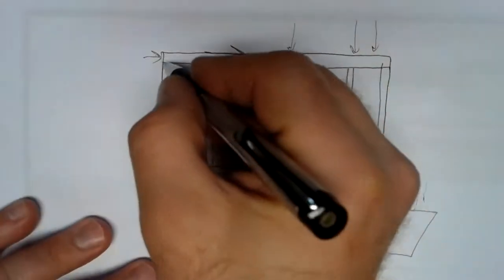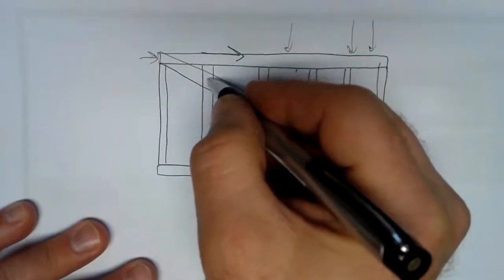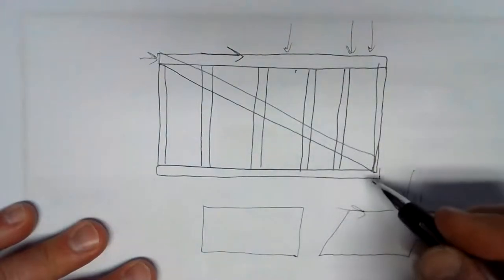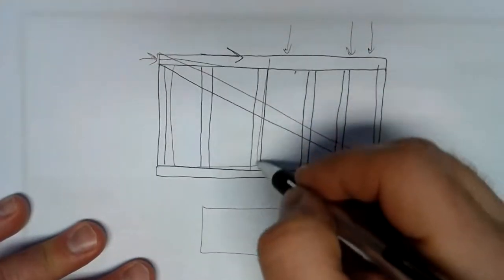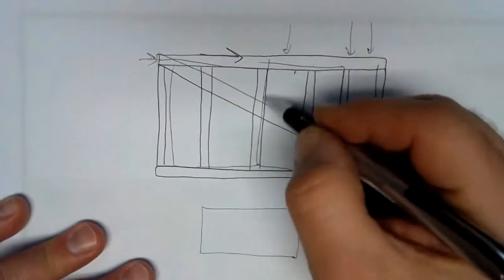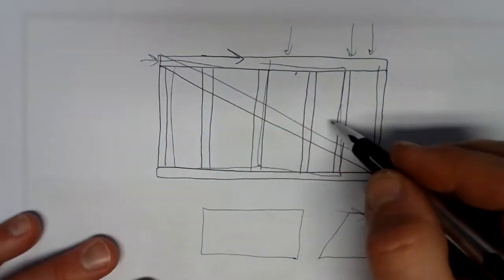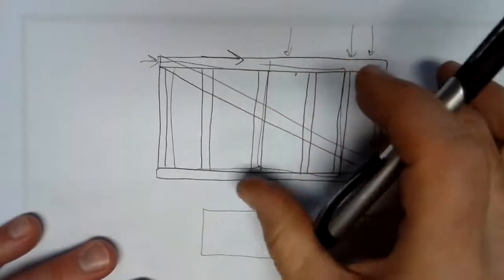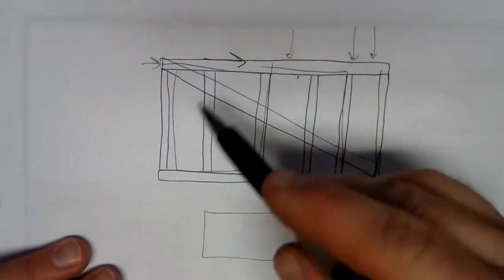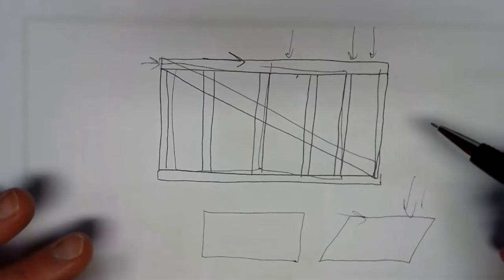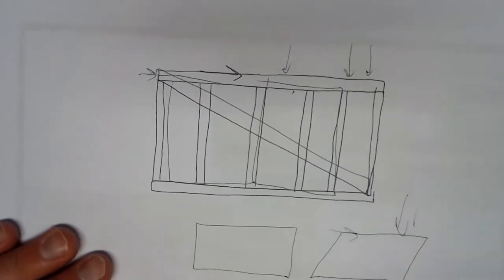You might put in a piece of wood across like this. That will keep this from racking. Another thing to do is put a piece of plywood there. Put some plywood sheathing on there. That plywood sheathing acts as what we call a shear panel, which prevents the whole structure from racking. So that's another example of where shear forces can come in and some of the problems that can be caused as a result of shear.